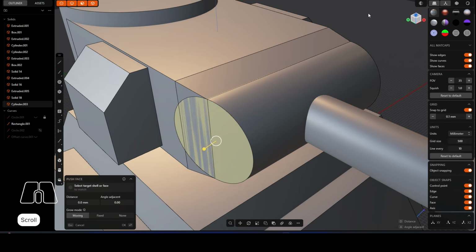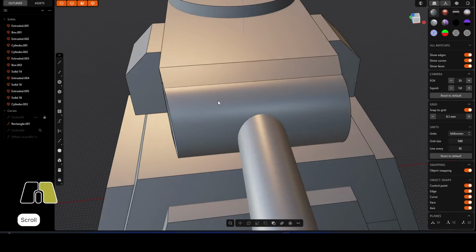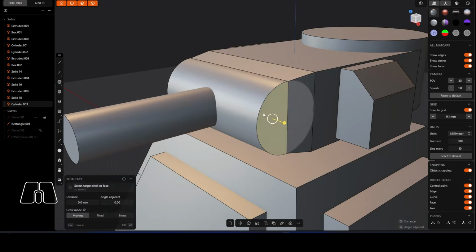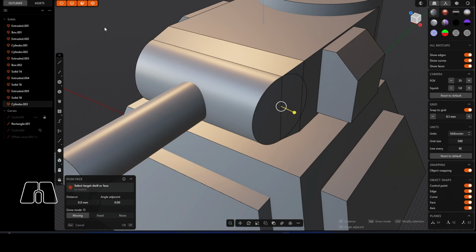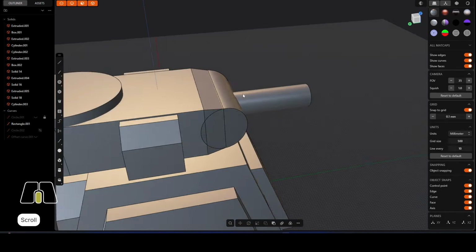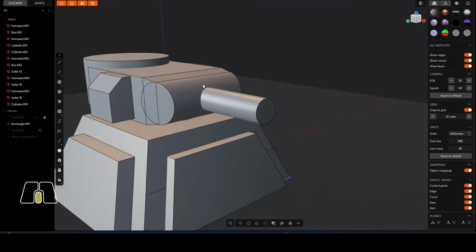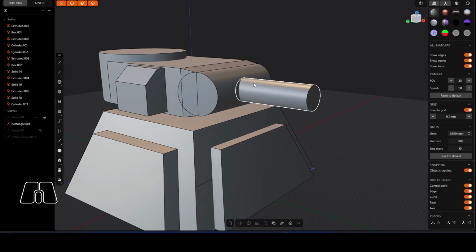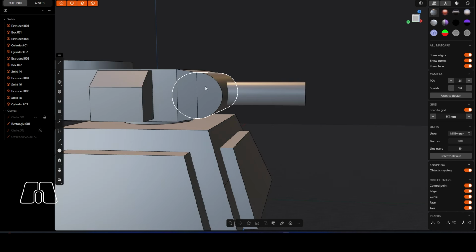So let's do this side as well. So we'll just line that up to the face, so you can see it's got face alignment there, which is nice. And again, we'll do the same here. So let's align that up. So that's pretty good going there. So now what we've created in effect is that sort of hinge joint. So that means that with this here, so we've got the pivot, that means it can go 360-degree round. And again, I'm being a bit of a geek here, but you know, with the hinge joint included, it means it gives this cannon the angle to shoot.